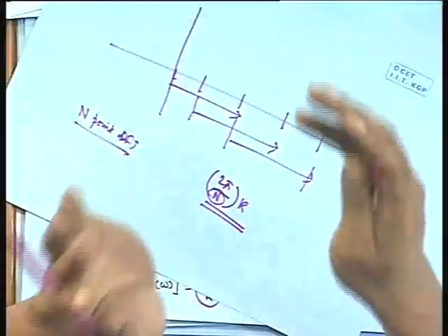If you do a 10-point DFT, you get the DFT at certain frequencies, and if you do a 100-point DFT, you will get it at a much finer frequency resolution. So in the first approach you are losing resolution because you are averaging. In frequency you are averaging. So it is quite obvious that you are losing resolution.